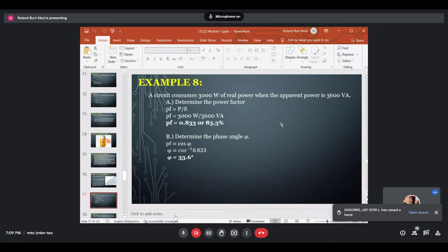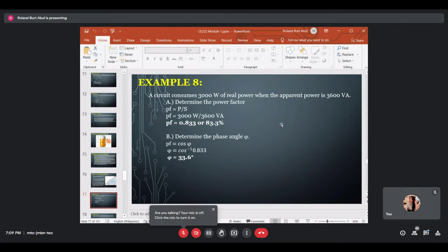In a single-phase circuit or balanced three-phase system, the power factor can be measured with the wattmeter, ammeter, voltmeter method where the measured power in watts is divided by the product of measured voltage and current. Equipment specifications provided by the manufacturer and motor nameplates often designate the power factor. Where the AC waveform is purely sinusoidal, true power and apparent power can be thought of as forming the adjacent and hypotenuse sides of a right triangle.